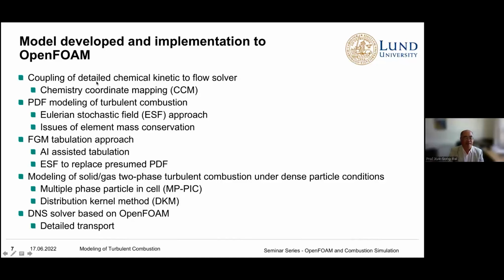These are detailed, direct coupling with chemistry, but the FGM model, many of you know it. The FGM tabulation approach is really the preferred one if it's accurate enough to do such simulation. However, for low temperature combustion engines and many other applications, the FGM dimension can be very large. So the FGM table can be many terabytes, and it's very difficult to use in engine simulation.